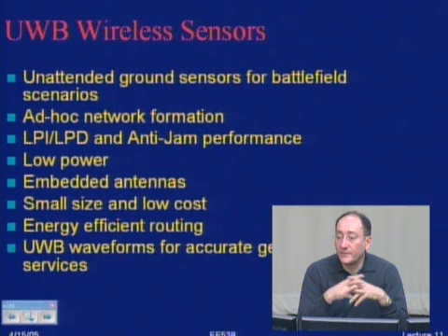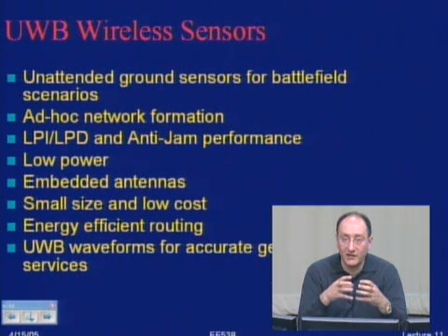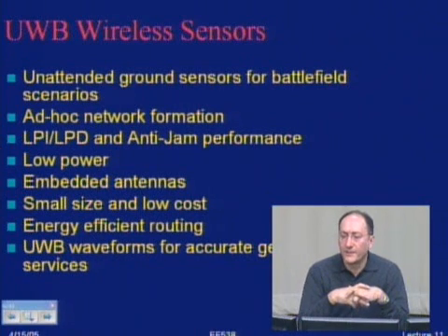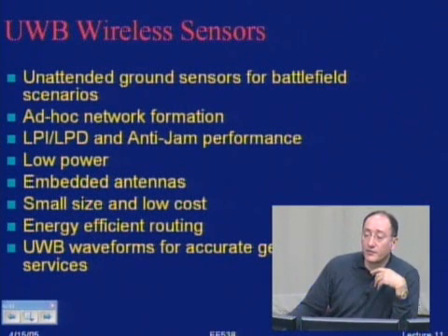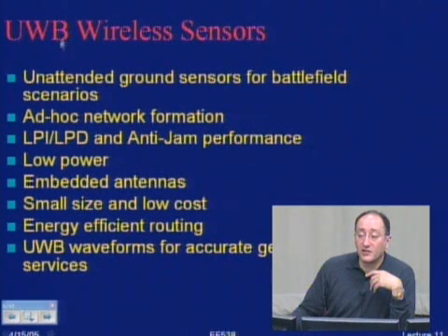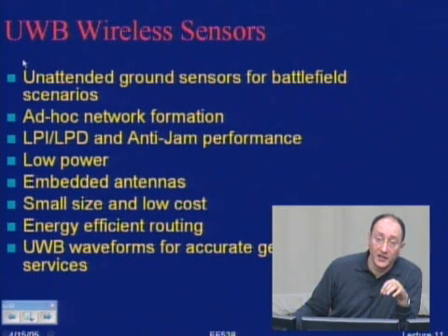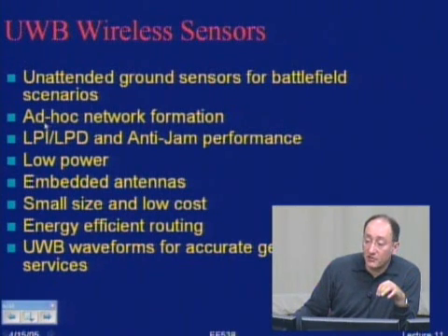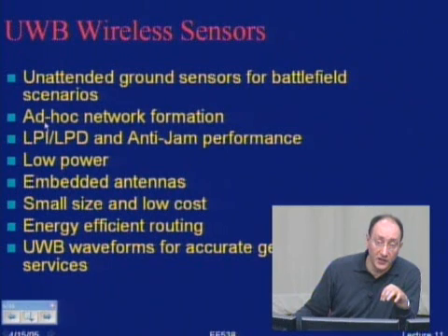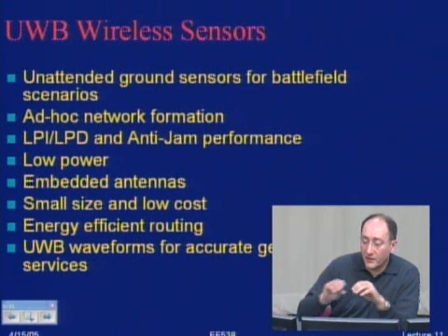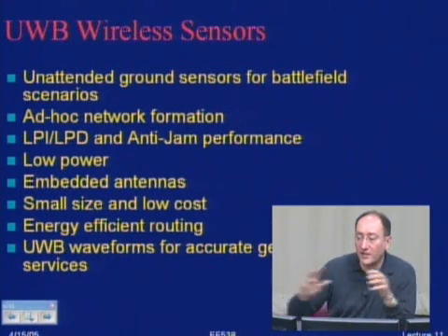So they have to be self-healing. They have to come back and communicate with each other. But anyways, ultra-wideband technology is considered for that type of application, especially by the military. For military, the issue of security also comes into the picture. The wider the bandwidth, the easier it is to provide security, because your power gets spread over a wider area.